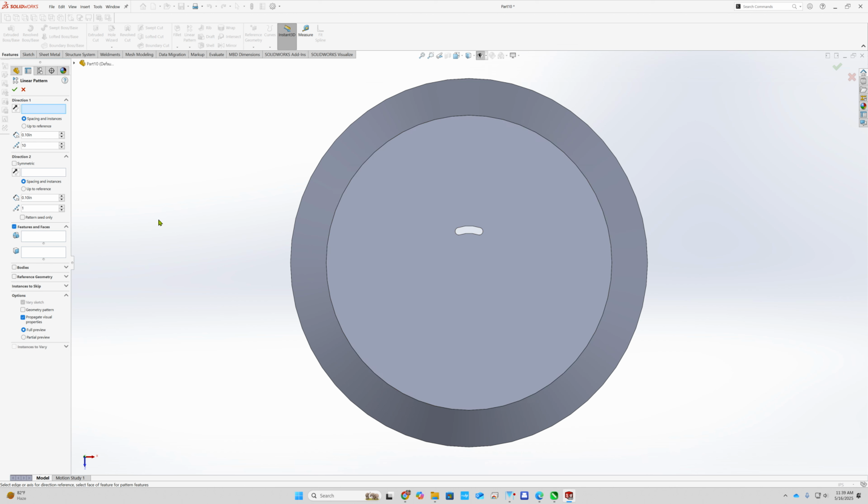I spent so much time trying to figure this out that this is where it's going to pay off watching this video. You got to go to the feature first and tell it you're going to repeat this extruded cut feature. Now it gives you the dimension to choose from as your direction. You got to pick this dimension as your direction. And see, it's trying to repeat it. How about change the spacing 0.18 and change the number of them to 8. And we got ourselves a wing-ding linear pattern using a vary sketch.